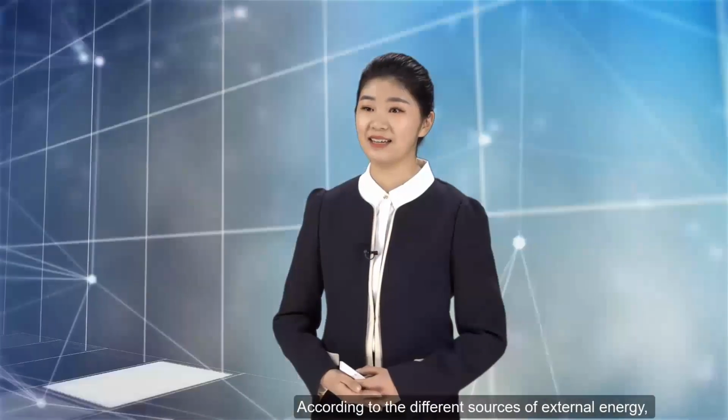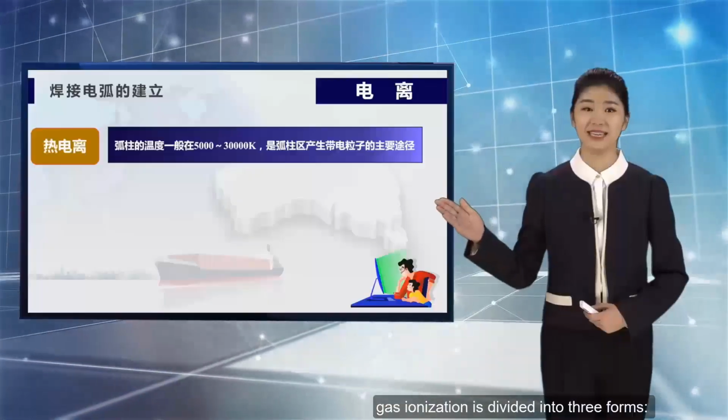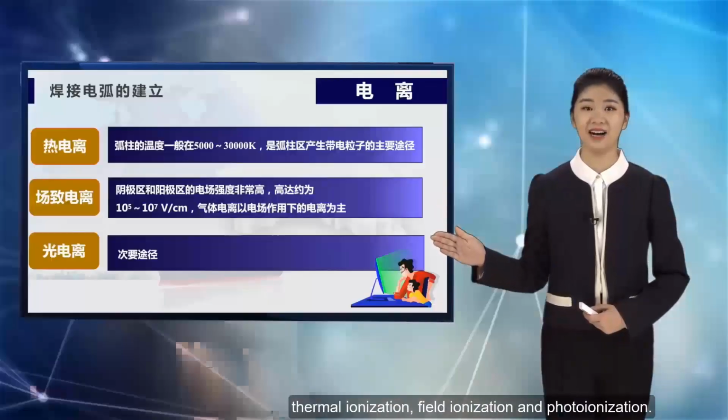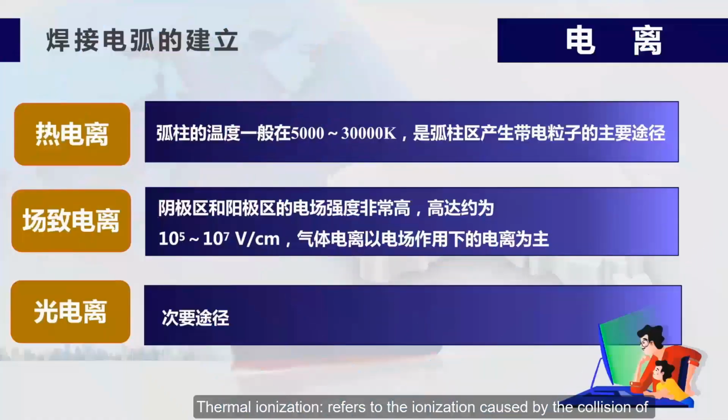According to the different sources of external energy, gas ionization is divided into three forms: thermal ionization, field ionization and photoionization. Thermal ionization refers to the ionization caused by the collision of gas atoms, or molecules, with high kinetic energy at high temperature. Since the temperature of the arc column is generally between 5,000 and 30,000 kelvins, thermal ionization is the main way to generate charged particles in the arc column.